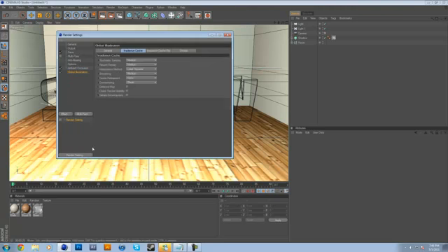We'll pop on global illumination. Now, this is the big one. This is the one that's going to give us our sort of realism look to it, because global illumination is pretty much essential if you want things to look real. So in our GI mode, I'm actually going to change that to IR plus QMC of a still image. That will actually, how do I explain it? It gives you shadows in your global illumination.